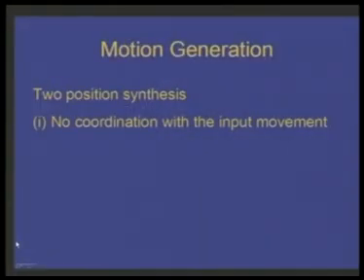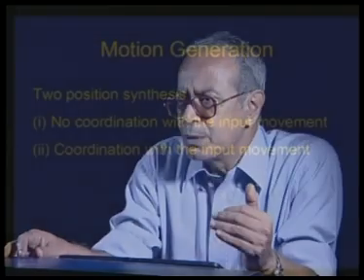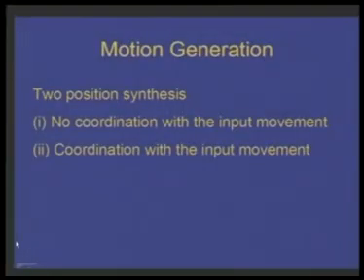This two-position synthesis can be, as I said earlier, without any coordination with the input movement. That means we are satisfied so long the coupler takes up the prescribed positions numbered 1 and 2, and we are not bothered what is the corresponding movement of the input link. Then we shall discuss how to solve the same problem of two-position synthesis coordinated with the input movement. In the second type of problem, as the coupler moves from position 1 to position 2, it is desired that the input link should be moved by a prescribed amount, say theta 2.